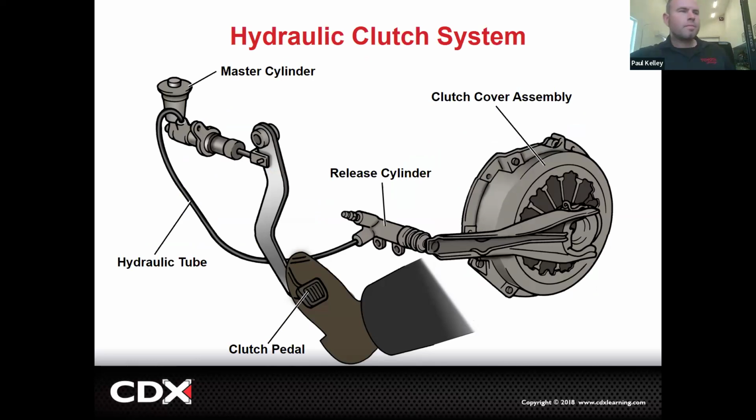So here's another angle. You guys can see pedal goes to the mat. Here's a fun one. You push this clutch pedal down. If this seal, right, because we don't have a dual chamber, this isn't a safety brake master cylinder. This is just a regular master cylinder. If this seal is leaking and you push the clutch pedal down and brake fluid comes out and gets on your toes, you know that it's that clutch master cylinder. Makes sense?